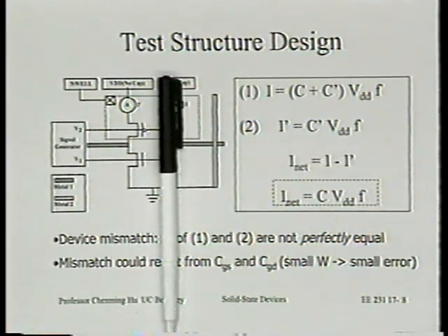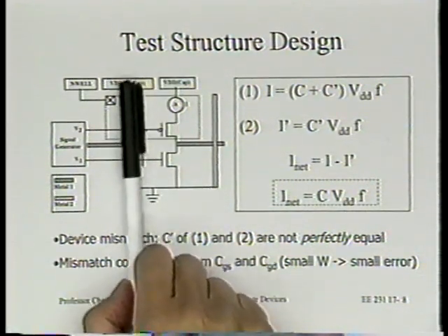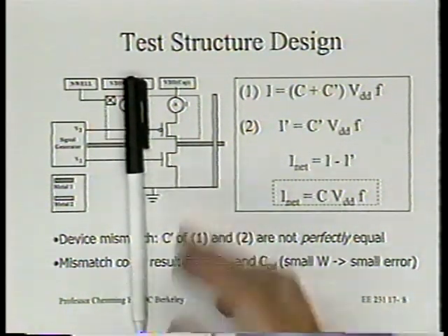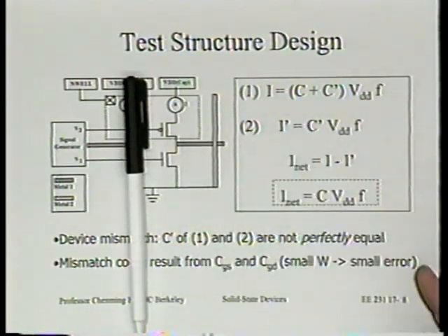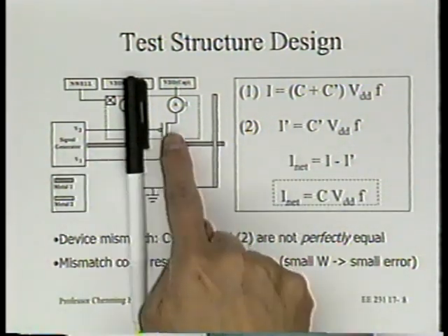I'll describe to you the relationship between the clocks in a moment. I guess I should show you on this side first. Look at this side. It's the same thing. It looks like an inverter, but it's not, because the gates are driven by two different clocks.